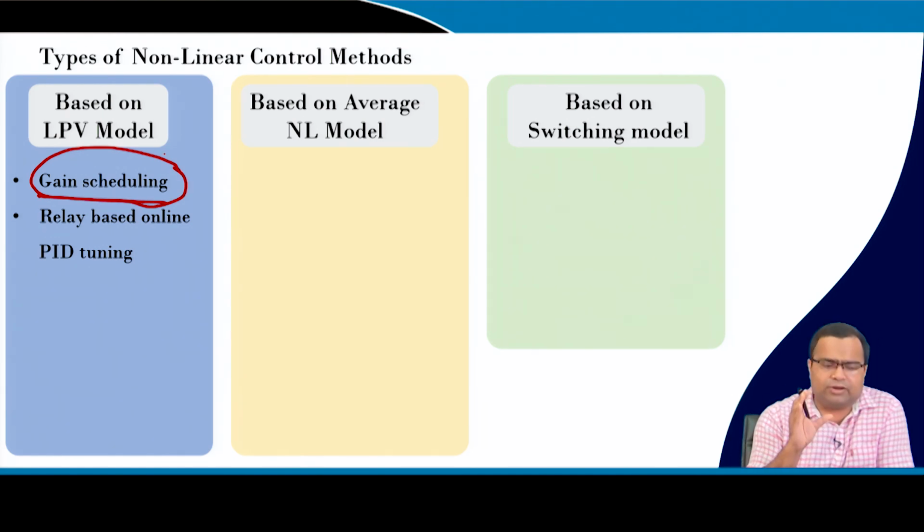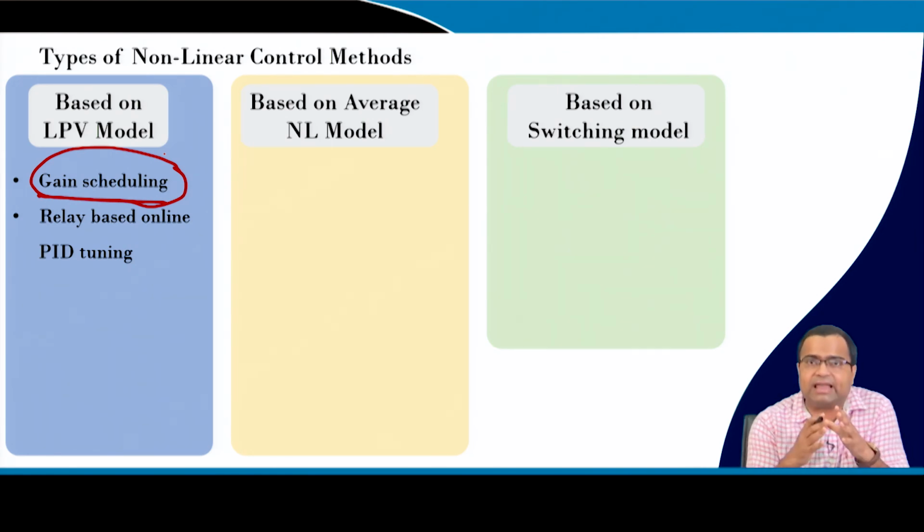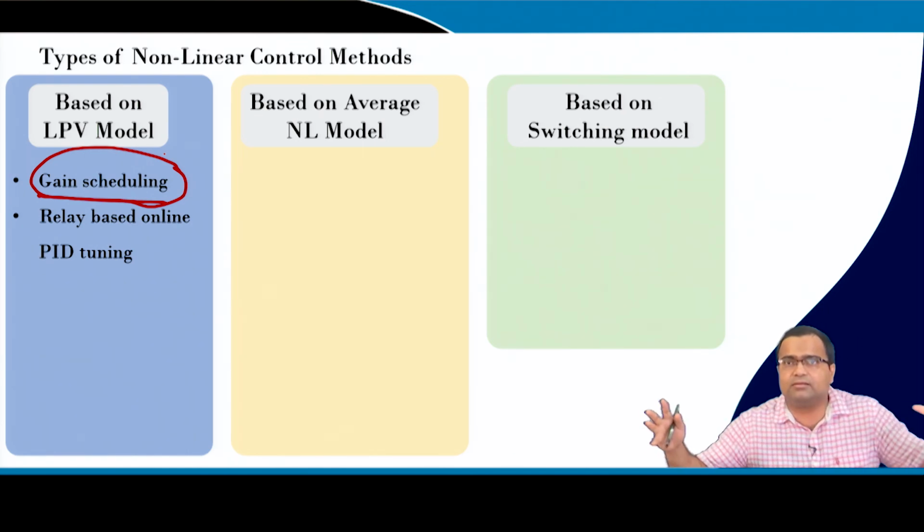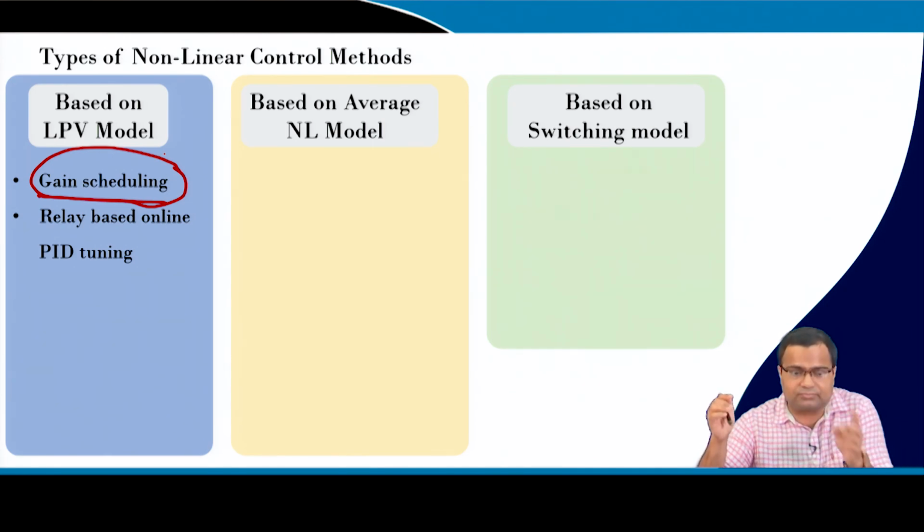We have voltage mode and current mode control, we have taken the small signal model, and we have derived an analytical way of compensator design to achieve certain crossover frequency and phase margin, and those equations can be used, and the parameters we can tune in real time to get a reasonably fast transient for a wide range of operating conditions.